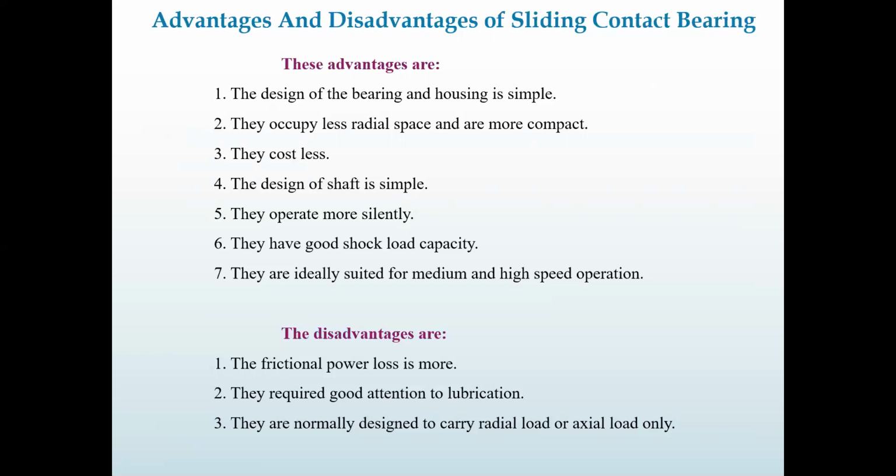Then with respect to the design of the shaft, as the design of the bearing is very simple, it is very easy to calculate the dynamic or static forces applied over the shaft, and by using the torsional, bending, or combined load formula, you can easily design the shaft.